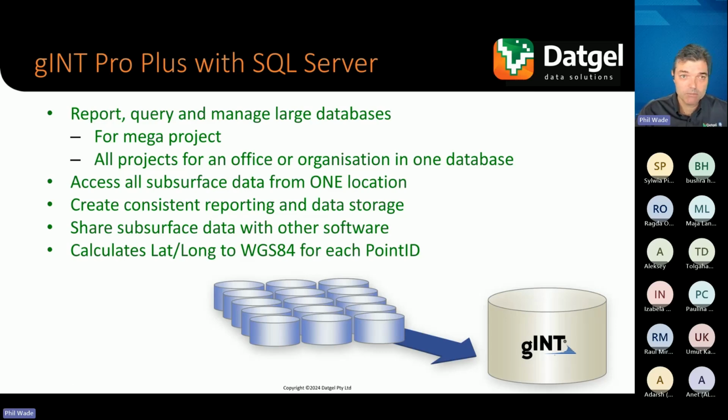Now you also have the option to use SQL Server. That's only with gINT Professional Plus, the highest product that gINT is available under. And this will allow you to have gigabytes of data in one database, where with Access, you can only really have 1 gigabyte database sizes. Otherwise, it will get too bloated and basically stop working.